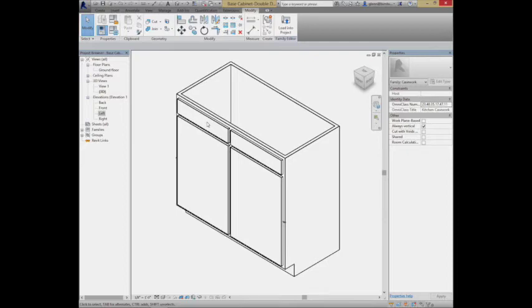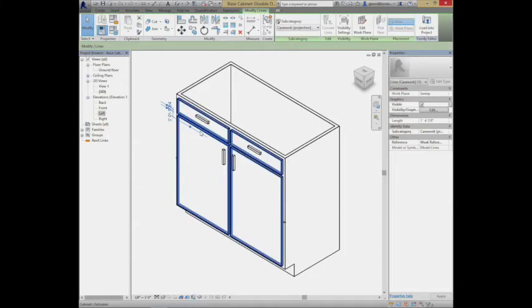So if I want, for example, a cabinet that has glass doors in it as opposed to solid doors, I might take this one and just adjust the profiles or adjust the extrusion. Let me put the door handles back for a second, because I'm going to use them in a second to do something else. So I could take this extrusion,